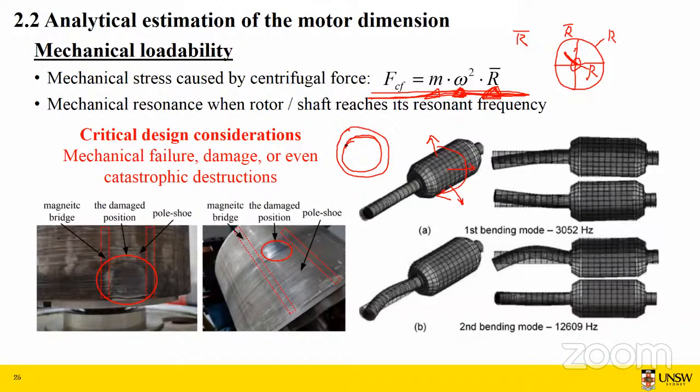When the plastic deformation happens, the rotor may deform like this, and the deformed part may touch the stator inner surface and cause this kind of damage. This is actually a good situation, because normally when plastic deformation happens, you could get a more severe mechanical failure or damage.